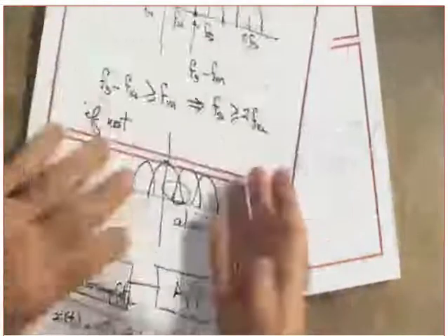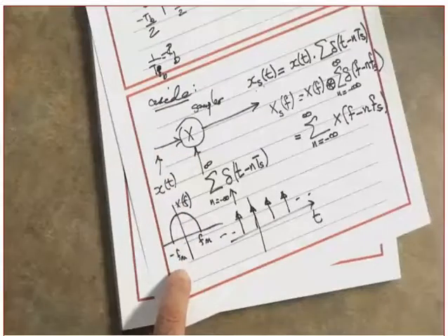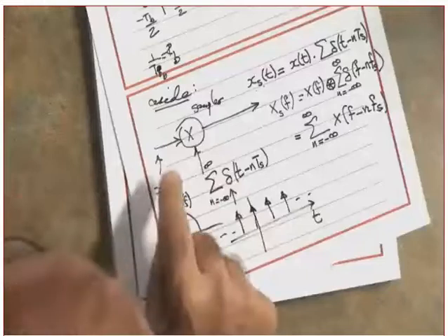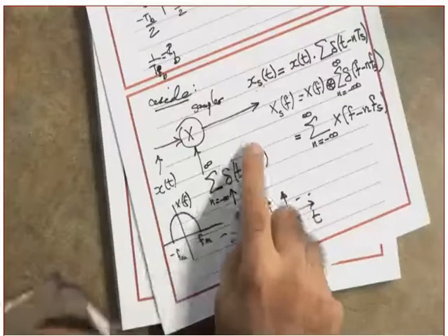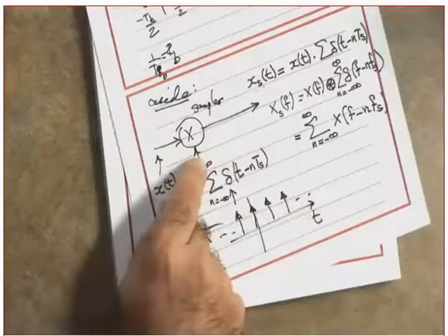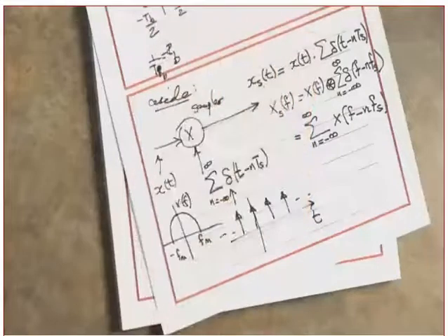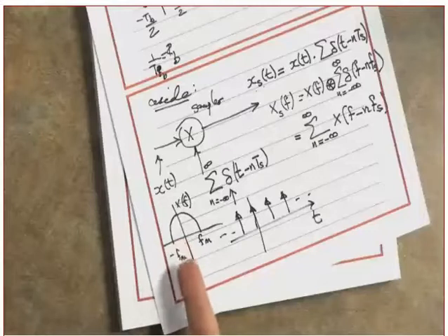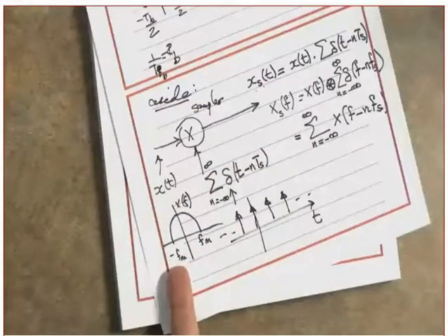Did you get it? Okay, what I want you now to see in the homework is that if this signal is a passband signal, is this a passband or is it a baseband? Baseband. Why? Because its spectrum is around what? Around 0, a low frequency. But if this signal was a passband signal centered around, for example, IF, you will see that if you choose a sampling rate at least twice the bandwidth of the signal rather than the what? The highest frequency. By the way, in this case, the bandwidth and the highest frequency component are the same. Do you agree? Because you are measuring it from 0. Yes or no? What, by the way, is the bandwidth of this?